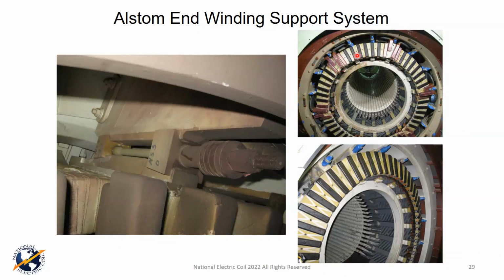We went in there, and when we did that, the other 5 phase areas ranged anywhere from about 121 to about 126 or 127 hertz. And that means that these things had a resonant condition and they were vibrating like a paint shaker. And that's what caused stress cracks in these phase connections, which led to that failure. Now we corrected it by the geometry of those connections, putting in extra blocking that you see here. And we also put in an additional inner surge ring, I believe. We reused their tensioning devices.